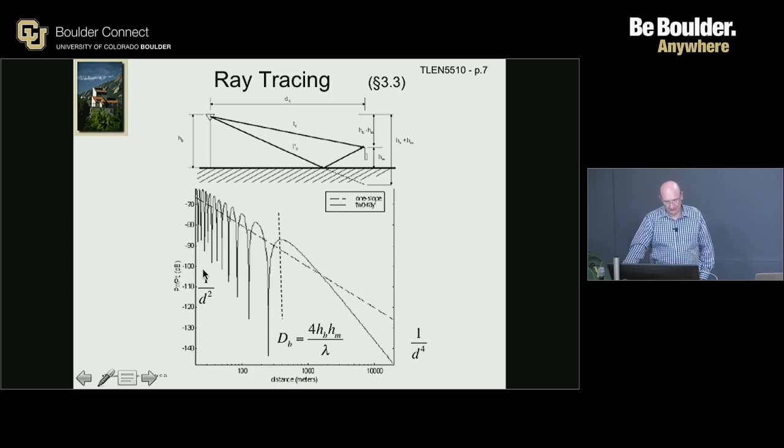But when they cancel in opposite phase, again, if you assume that there's no loss and the distances are more or less the same, they can be almost the same signal in opposite phase. That means it goes almost to 0, which means that those fades can nearly go to negative infinity. Practically, they can be very deep, 20, 30 dB. And that's what you'll see.